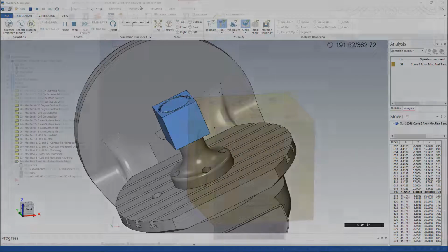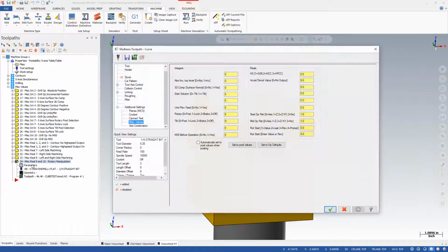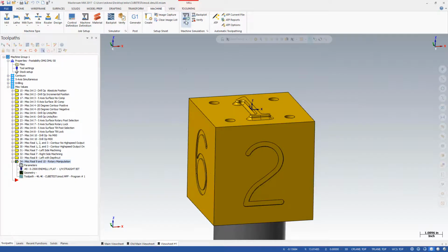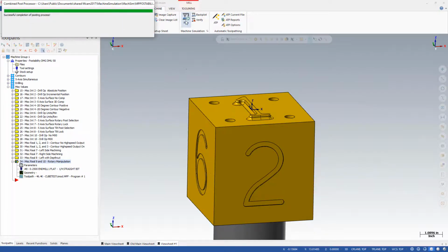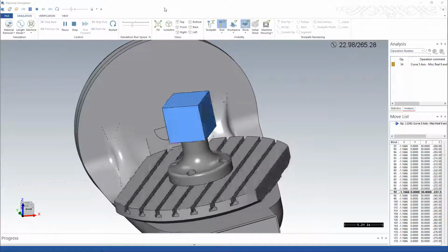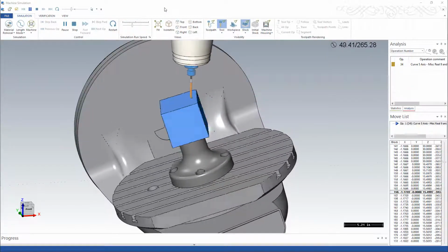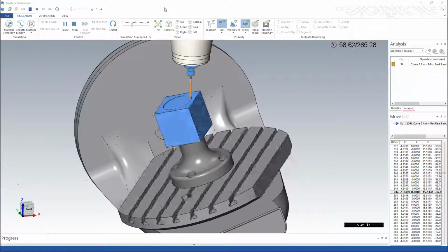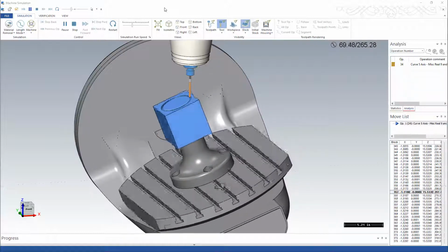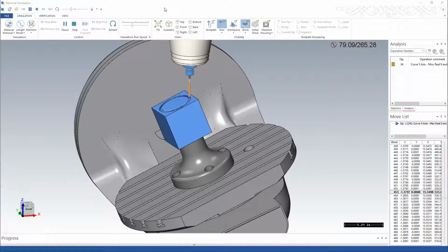The toolpath is doing less than 1 revolution after the unwind, so if we start the operation in a more negative C position, the entire path could be cut in one go. Set real 9 to 3 for revolutions, and real 10 to -1, so the path starts at negative 360 degrees from the current position. During the posting, there is no prompt about an unwinding occurring, and backplot confirms this. The toolpath now starts at negative 450 degrees, 360 degrees less than previous, and fits into the machine's limits for C.